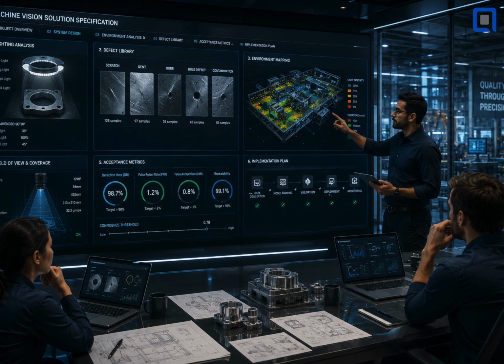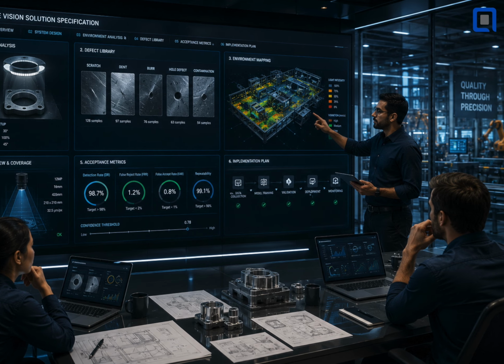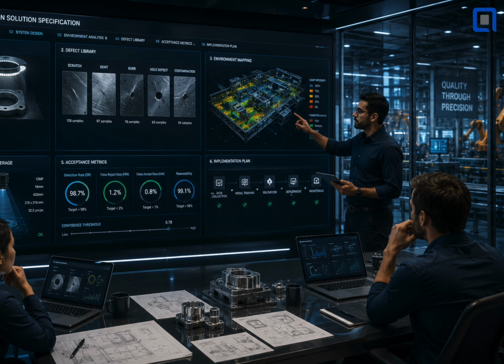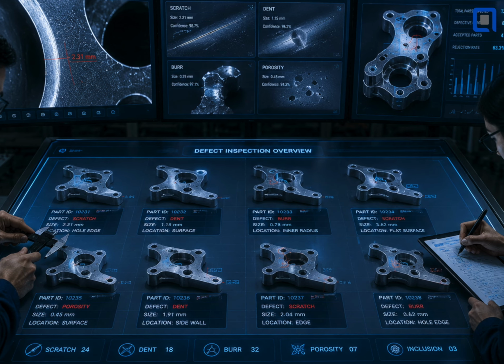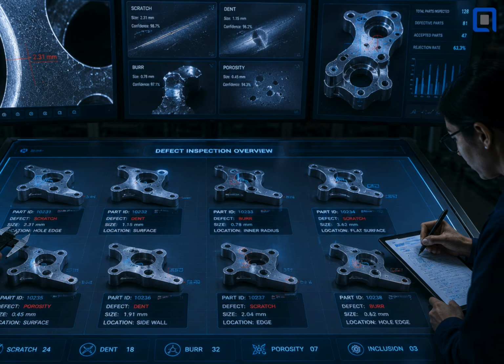The 98% to 75% gap, when we looked at the conditions, 3 things weren't in the spec. The lighting in the production area differed significantly from the demo room. The parts arriving on the line had more surface variation than the demo samples showed, and there was no defined false reject rate, so the system had been tuned for accuracy on the demo set rather than the real operating trade-off.